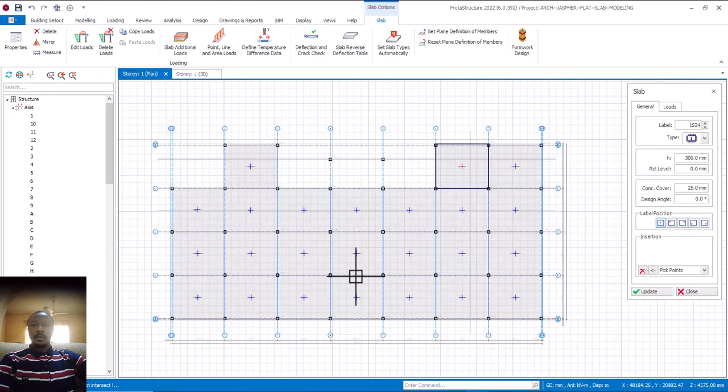And one thing about a flat slab, as I said that I'm going to be explaining, is that your flat slab must be typical, in the sense that whatever column is starting from the ground must be the same column that is going up. So you must try your best to ensure that the structure is typical.